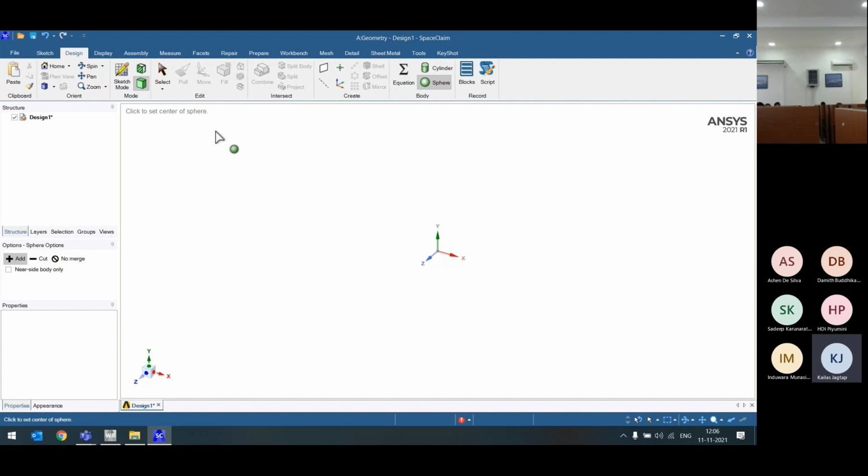So what kind of data losses happen and why? The algorithm used in different tools is different, so whenever you import that model into Ansys, there are chances of certain data losses. Like some edge is split, meaning a continuous edge is split into two parts, any surface is missing from the object, or extra edges or extra points are created.